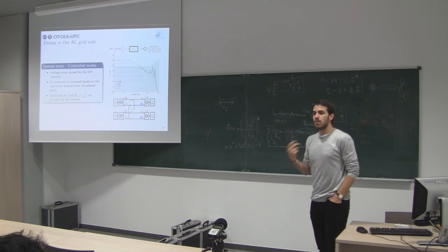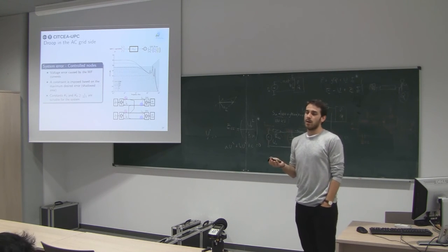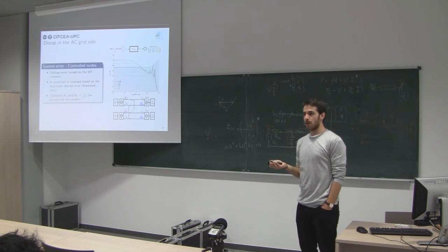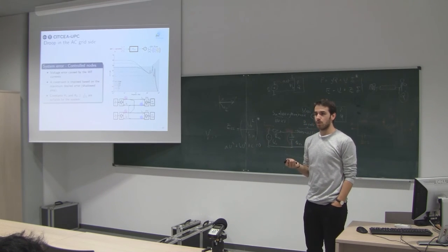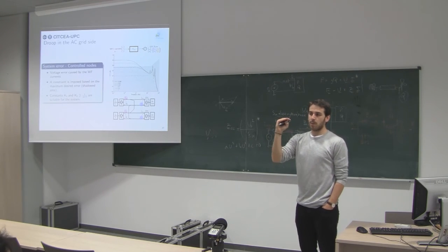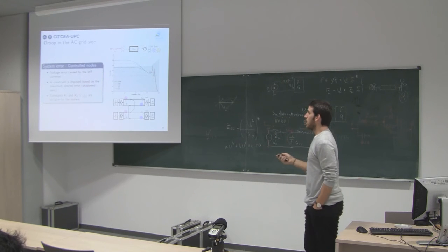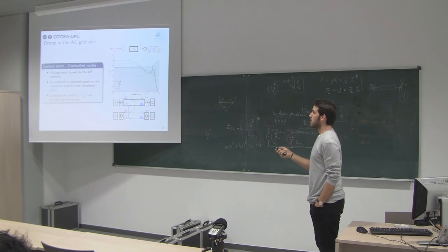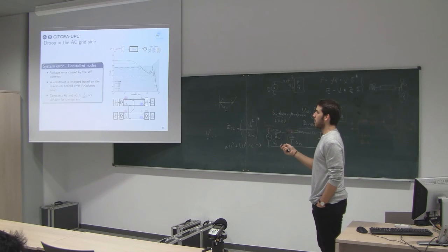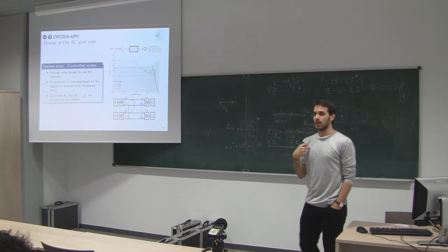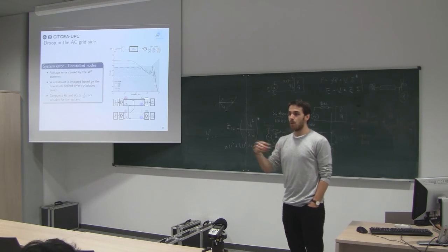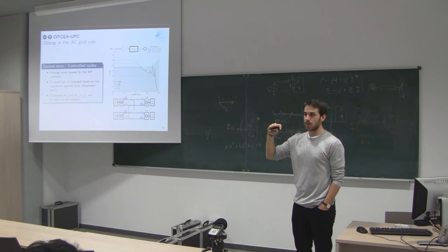And then we decided that the worst error we wanted to have in the system was 1.05 per unit, so a maximum deviation of 5%. If we know this maximum input, and the maximum output that we want to allow on our system, we can limit the gains of the system.